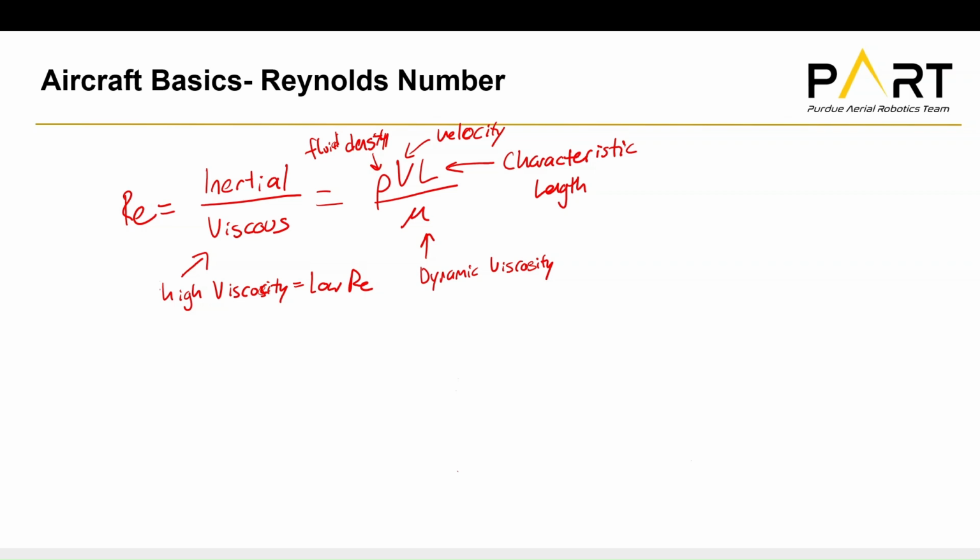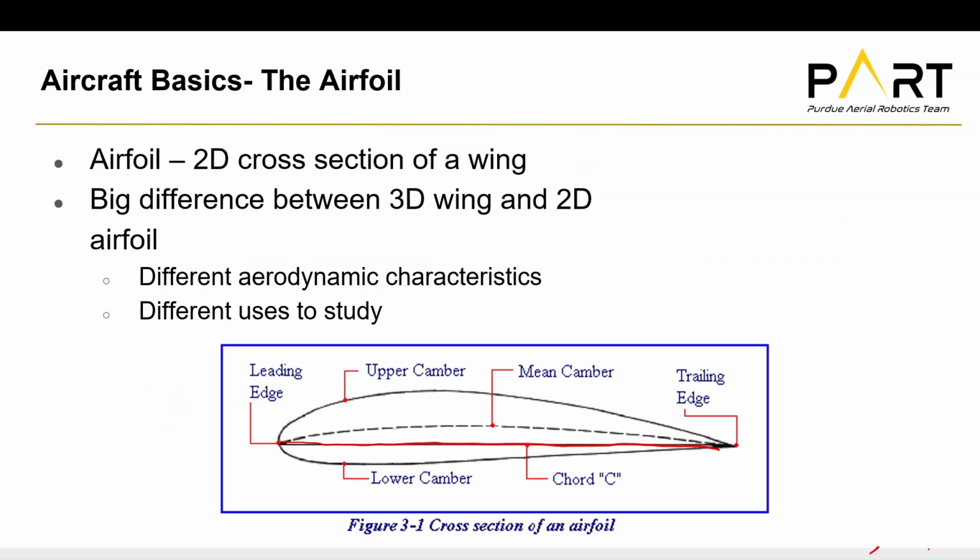And for plumbers, you'd be looking at pipes. In this case, your characteristic length is actually the diameter of the pipe, d. So their Reynolds number would be rho v d over mu, just replacing that L with d. And so let's say that you have two pipes. You have a high diameter.